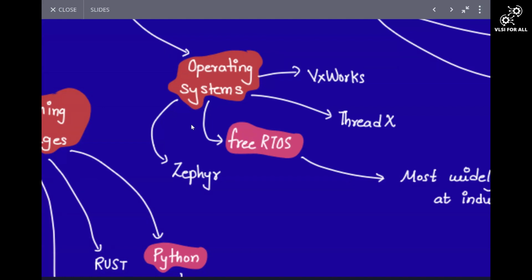Now what we have to do here is, there are two tasks. One task is sensing the temperature, and the second task is sending this temperature data to the cloud. So what RTOS does is, it manages to do these two tasks at the same time. That means there are slots within the processor. In slot 1, you sense temperature. Next slot, you send this temperature to the cloud. Again in the next slot, you sense temperature. Again in the next slot, you send this temperature to the cloud.